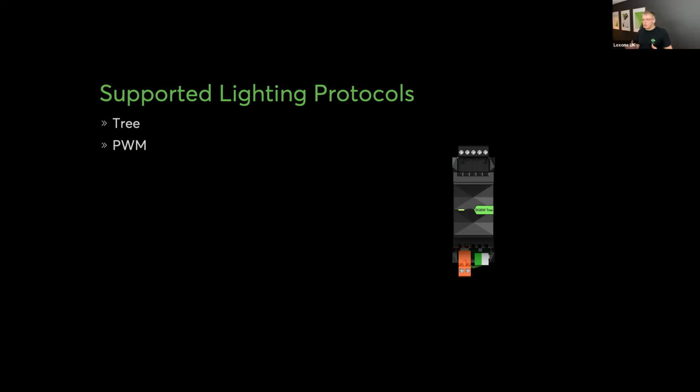Now, of course, the range of 24 volt lighting out there isn't massive. Of course, we've got the Loxone Tree fittings, we've got LED strips. LED strips are flexibly available all over the place, but your regular lighting, like your downlights, pendants, your general lamps, they're not necessarily off-the-shelf products. Therefore, most people point towards either Tree lighting or they'll point towards your traditional mains dimming.